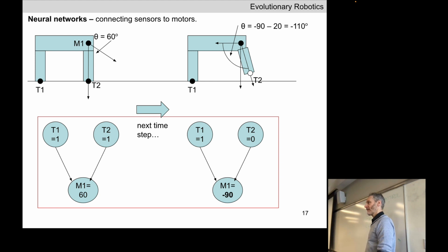Are forces calculated first for the main link and then for the other one? It's a good question. So what order are forces calculated? For all intents and purposes, assume it's all parallel. So the force of gravity is acting on all three of these links, pulling them down. And now we have an additional set of forces that's also acting on these pairs of objects. It's not really about the order.